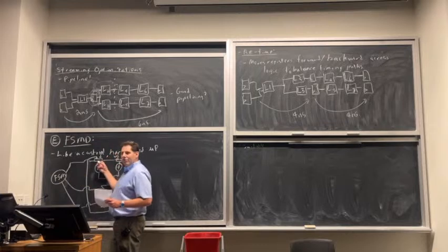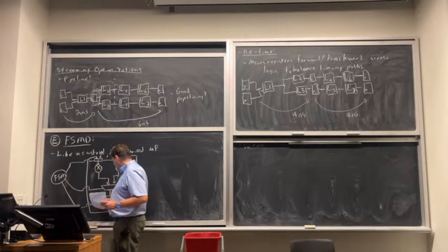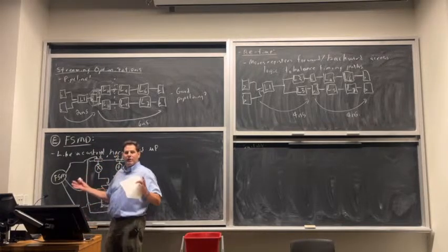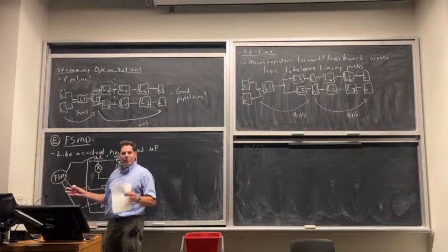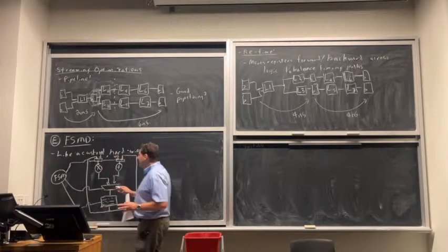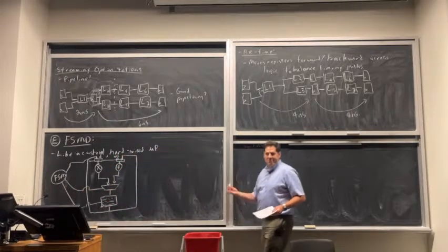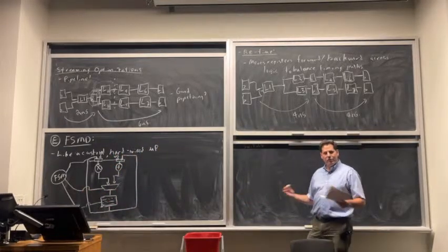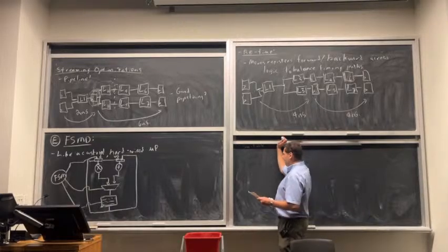As long as the muxes aren't too big, you know, if I had a huge number of registers here and the muxes start getting huge, well, then this might become inefficient. But if I don't have that many temporary values, so muxes are pretty small, then this is typically going to be less area than a fully streaming version because we're reusing hardware. Okay?